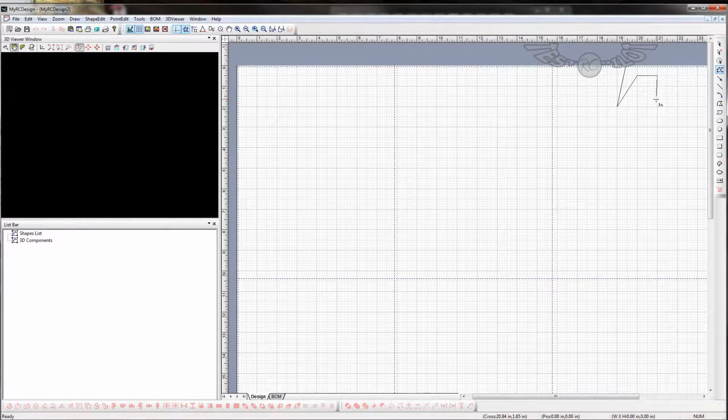And remember, you're going to want to make space for your elevator to go up and down. You don't want to have to put 2 servos in because that'll add extra weight. So your elevators need to be connected. So I'm going to create this little V right here so that when my elevator moves up and down, there's a space for it to move in. And then come back over this way.